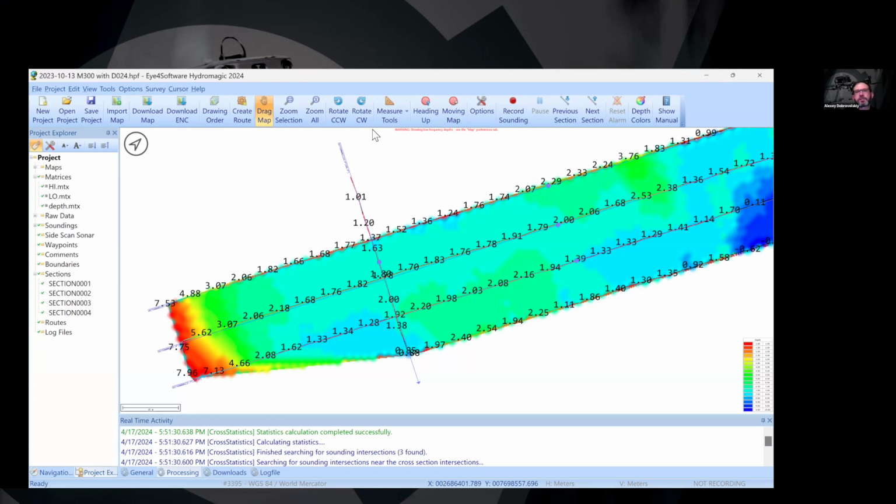Every technology has its own restrictions. For ground penetrating radars, low-frequency ground penetrating radars, there are a few restrictions. First of all, water should have low conductivity. Low conductivity means really low conductivity. For example, here in Latvia, in most rivers and lakes, we cannot use low-frequency GPR for bathymetry.